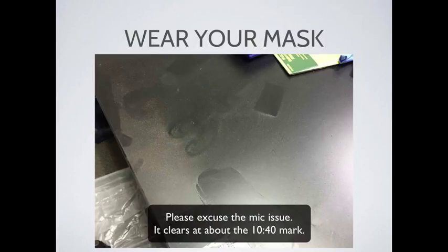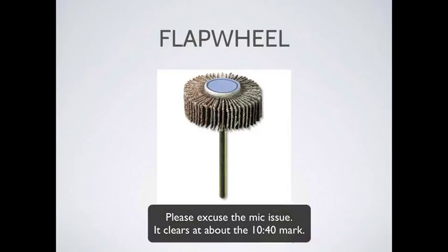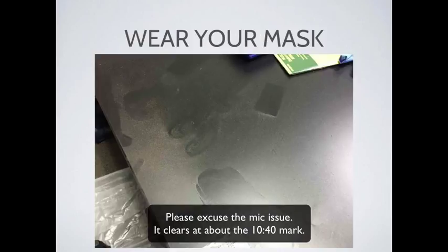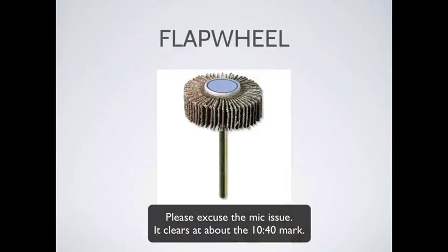So the sanding band wasn't bad, but because you're going to get a lot of copper flying off sometimes, you get copper sheet here. That's what the gray or the gold tannish colors are. The funny thing is that this board's solder mask was black, so I couldn't really tell. You'll see a lot of black powder on the edge. But when you start working with the actual board, where it's the green stuff, you can start to see this.